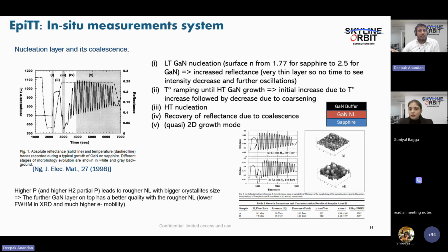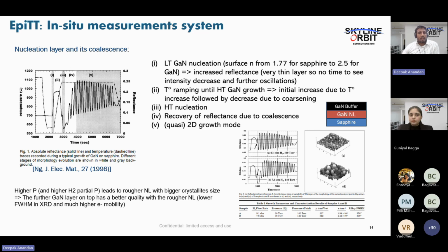But in terms of gate structure, you need to pay more attention, because having an ohmic contact or a Schottky contact on p-GaN material is quite difficult, since the carrier density is very low in p-GaN, and you will not be able to get an ohmic contact as good as with aluminum gallium nitride. Schottky contact may be a good option, but still it has a leakage current.